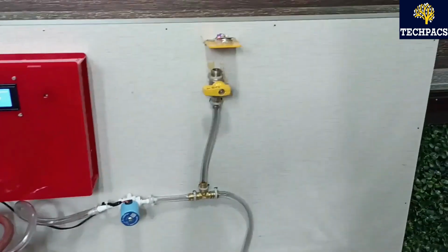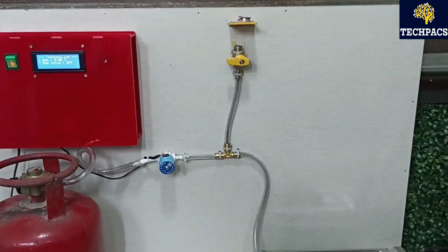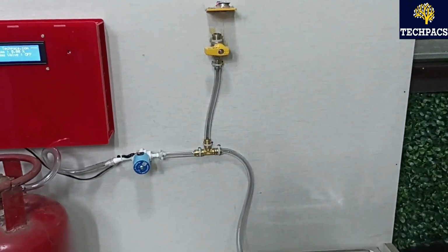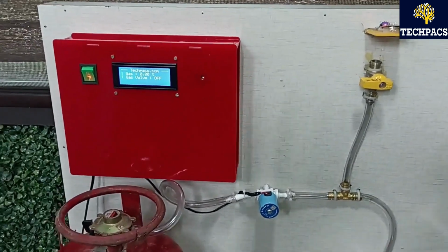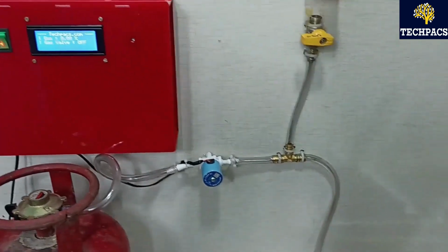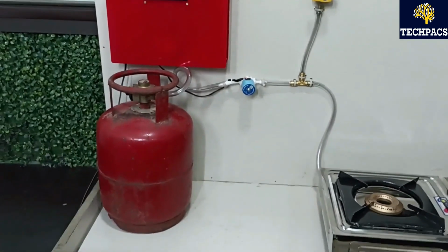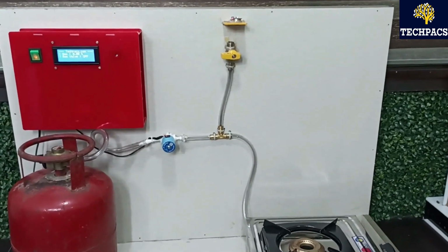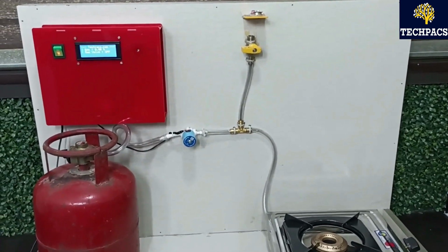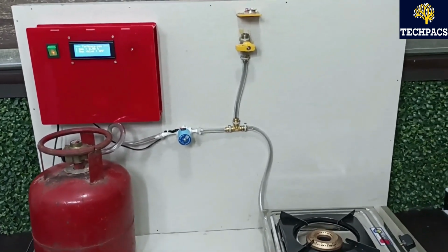Inside the control box, we have an ESP32 microcontroller that comprises an inbuilt Wi-Fi module through which we get the message of detection of gas remotely on our mobile through an Android application that we have developed using Java programming. Or you can get the same information at some other IoT platform as per your convenience. So as soon as we get the intimation of the leaked LPG gas in our kitchen, we can either have the automatic mode of our project on, through which it will automatically cut the supply down, or we can contact anyone at our home to take the required immediate action.